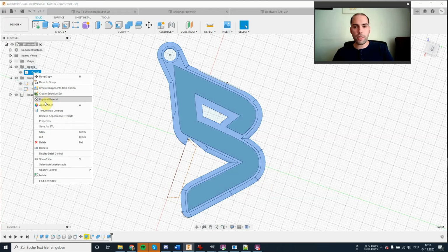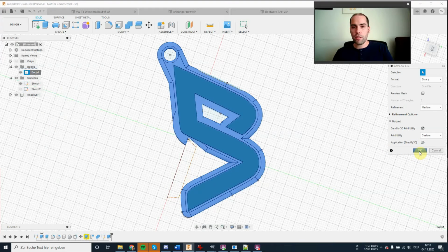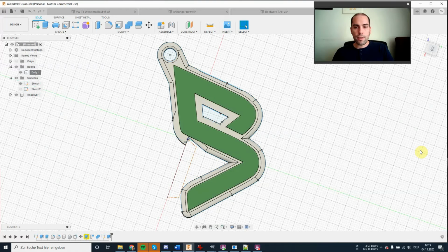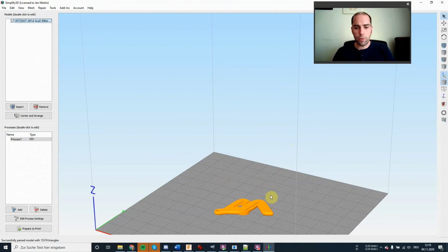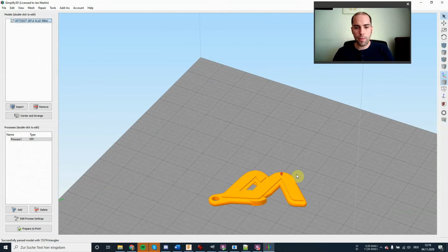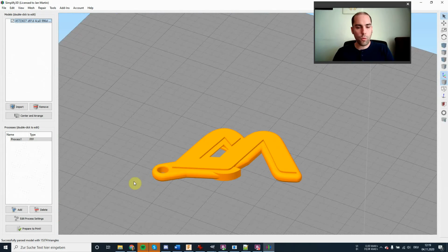We can't just directly give this 3D model to a 3D printer. Rather, we have to convert it into a set of instructions, mostly for movements, but also parameters such as heat. And yes, we need to create a file containing these instructions. Now this is the 3D printing utility. And with the standard settings, we can already see how the process is going to work generally.